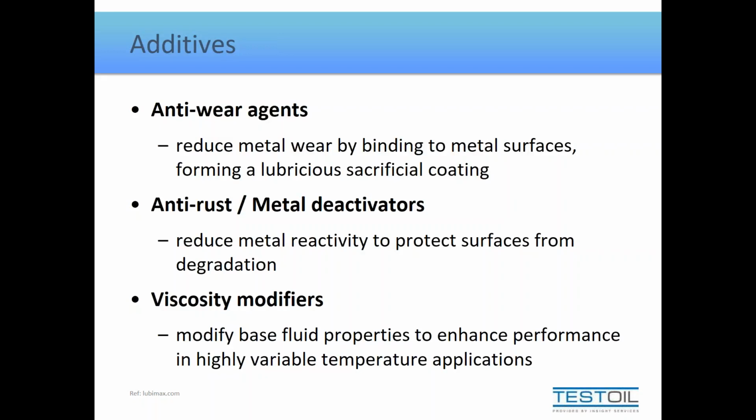We also have anti-rust or metal deactivators that are, of course, there to help the surface from reacting with oxygen and water. So they don't do much to help the grease prolong its life, but they will help the components from oxidizing and corroding. We also have viscosity modifiers. These are there to help prevent the lubricant from thinning as much as it would normally do at the higher temperatures. So this gives us an improved VI of the lubricant itself.